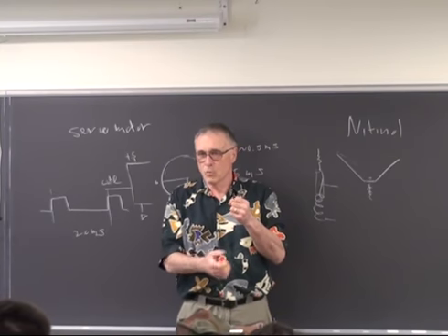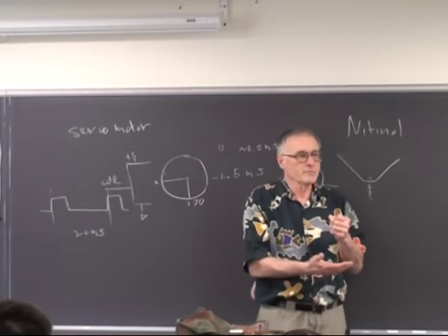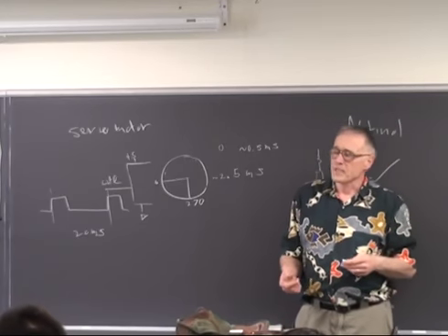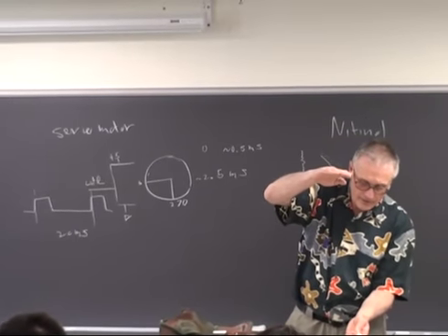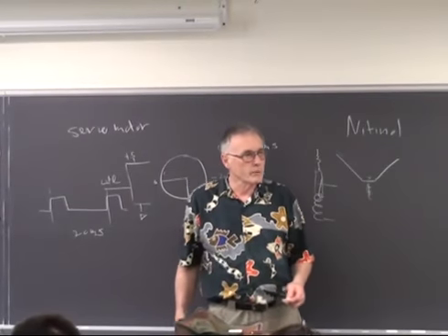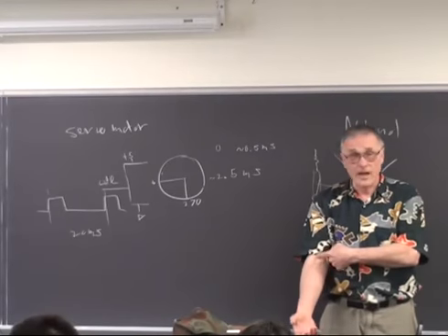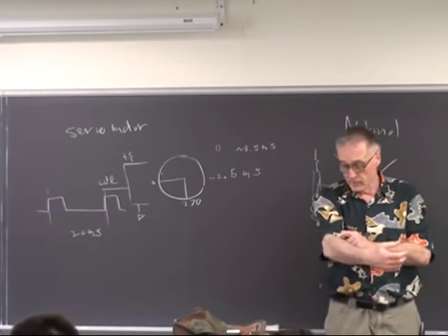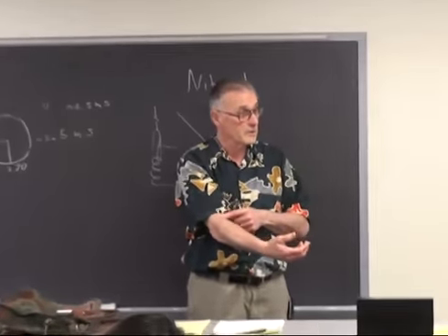So you get this wire that shrinks, and a wire that's 0.05 inches in diameter produces a few kilograms of force. You say, oh, well, 2 to 5%, who cares, right? Something this long is going to move a weight maybe half a centimeter off the table. That doesn't seem like much, but after all, your bicep only changes length about 2 to 5% when you contract. The reason you get so much motion in your arm is that you have a long lever out here to amplify the amount of motion that the bicep produces.